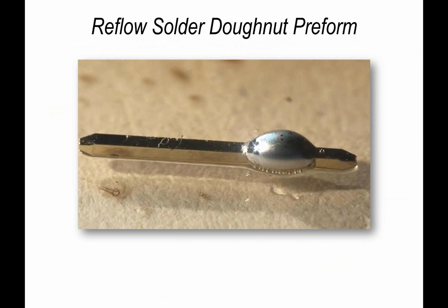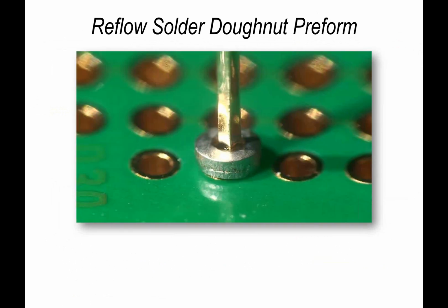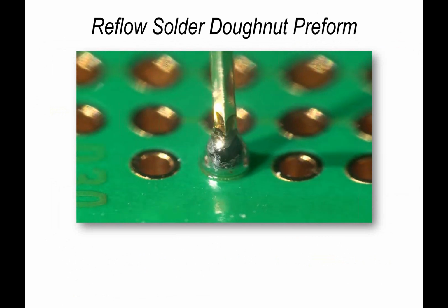So if you were working in nitrogen and you were getting too much of the solder drawn away from a surface, then you just turn down the nitrogen level or beef up the air content, and that would reduce the wetting. Second example, again just using the donut as an example. So here's a pin, it's in a printed circuit board. There was one donut there. This is a flux laminated preform, and we can just see reflow taking place. There is sufficient solder here to fill that plated through hole, and again there's no contamination to the rest of the pin assembly.